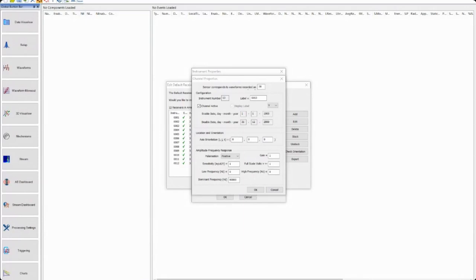Do we have to enter the coordinate of the surface or the actual position of the geophone? Oh, it's the actual position of our geophone. So we need to enter the northing, easting, and depth, the 3-dimensional position of our instrument as a coordinate.